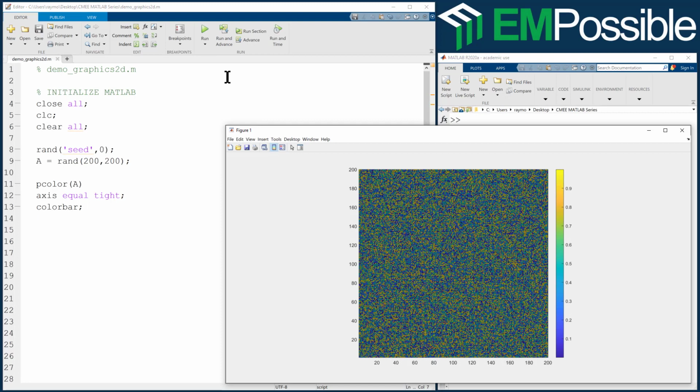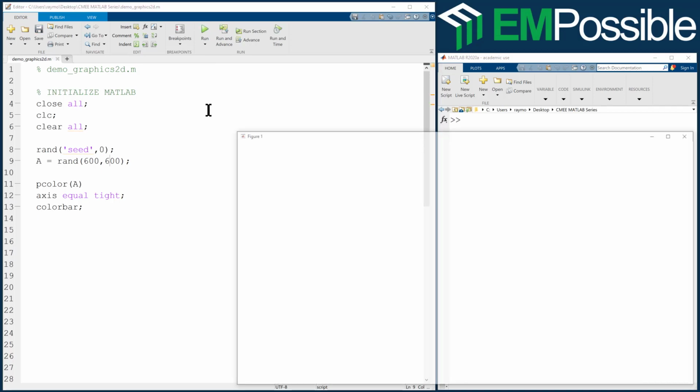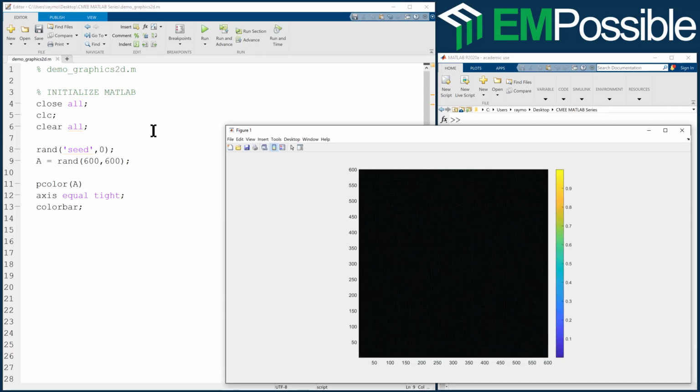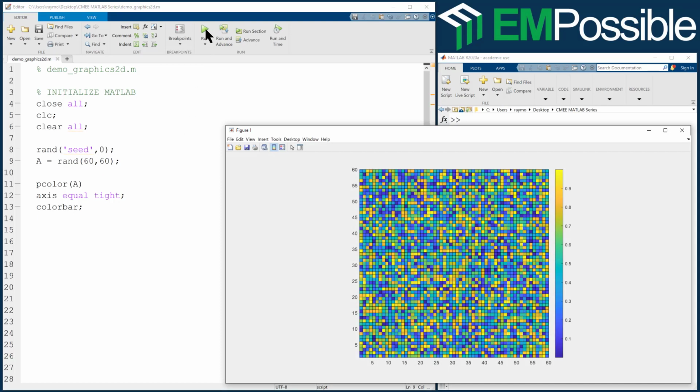Notice how dark this is. And in fact, if I were to up the number of points here, my plot is going to go completely black. Now, why is that? We can discover why that is if we plot less points. Look at what Pcolor is doing. It's putting black lines between each of those pixels. And so when we have a lot of those pixels, all we're seeing is the black lines.